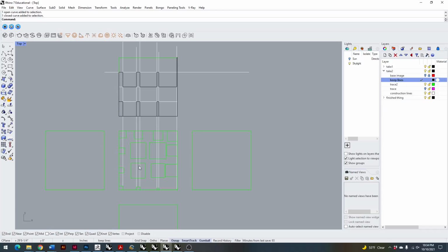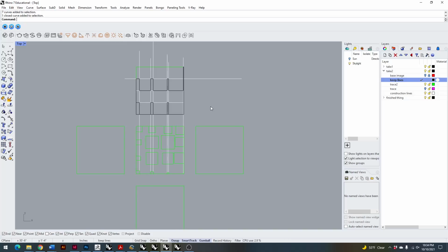So I know this gets a little bit abstract, but this corner here is shared by both, or this rectangular extrusion is shared by both this elevation and this elevation. So we'll need to use lines to project across to make sure that we're keeping things consistent. So the way to do that is we're going to use 45-degree lines to project across our drawing, 45-degree construction lines to project across the drawing to take information which occurs here and bring it onto this elevation.